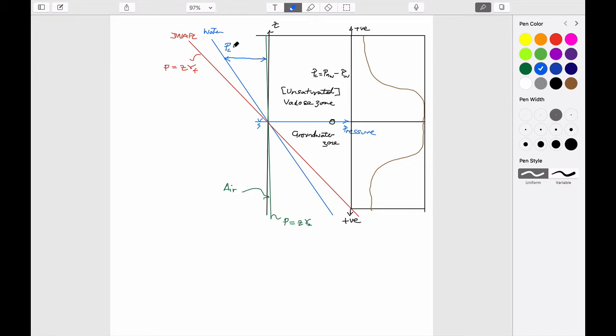Capillary pressure is equal to the pressure in the non-wetting minus the pressure in the wetting. The pressure in the wetting fluid, the water, is going to be negative, right? It's in tension, because this is by definition the atmospheric pressure. By definition, the location of the water table is where gauge pressure is 0. If we go down, we know that pressure increases.